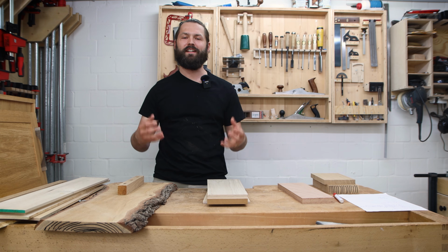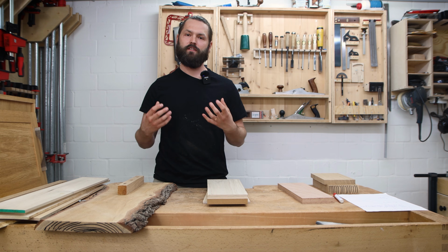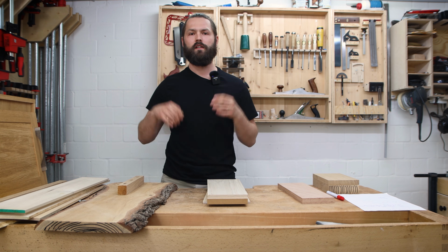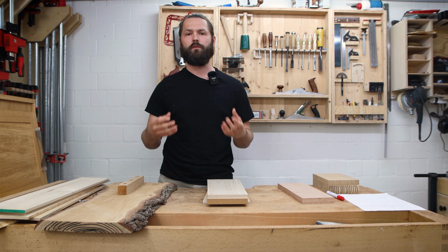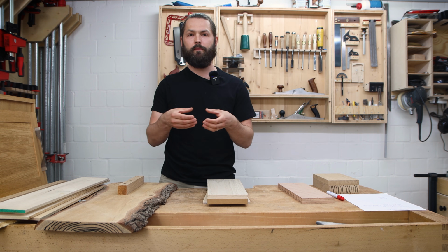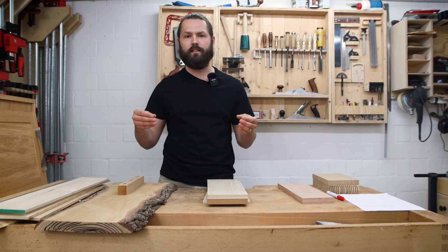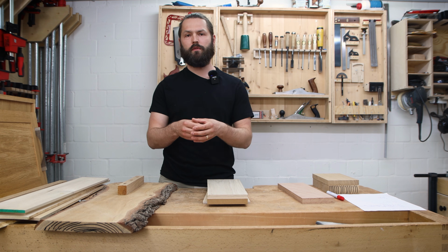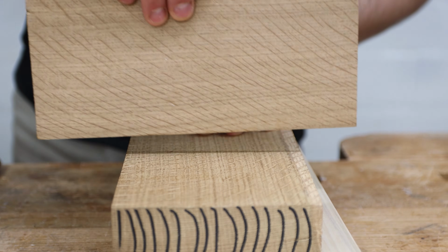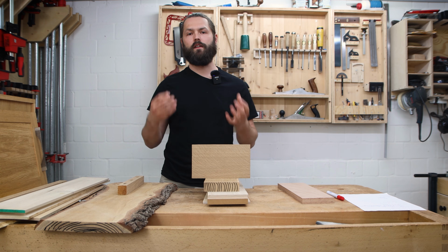I know this was a pretty deep dive into the topic, but I want to go over the key learnings you really have to take away when you deal with wood movement and want to build solid wood furniture. The most important thing to take away is that wood absorbs and gives away moisture, and with it, it changes its dimension. The most wood movement is taking place along the tangential axis of the wood, which in a flat sawn board is its width. This means that if you have a cross-grain joint like this, you have to account for wood movement in some way.